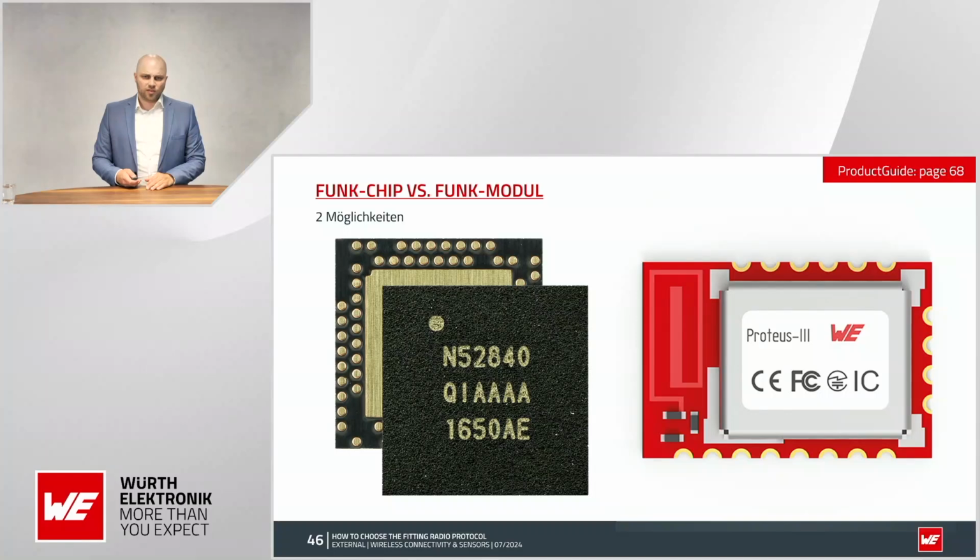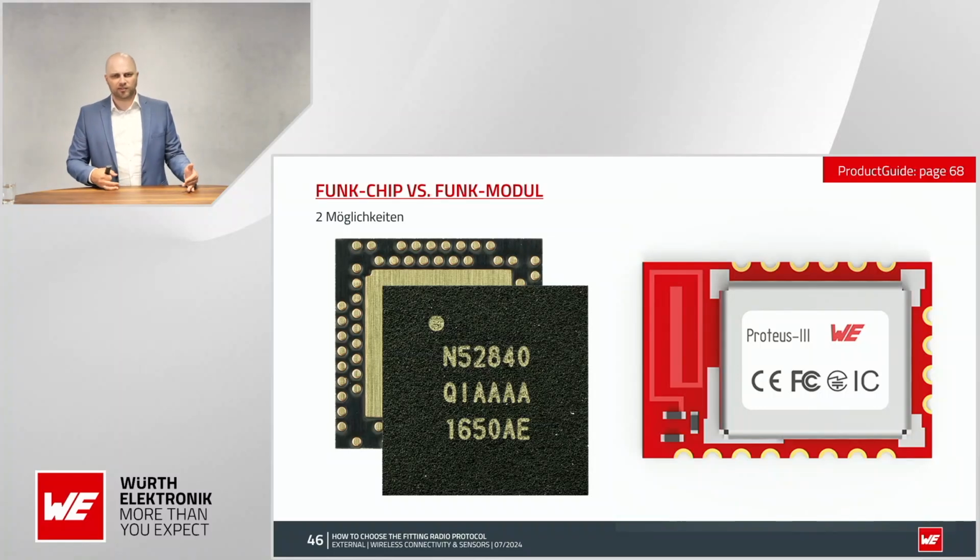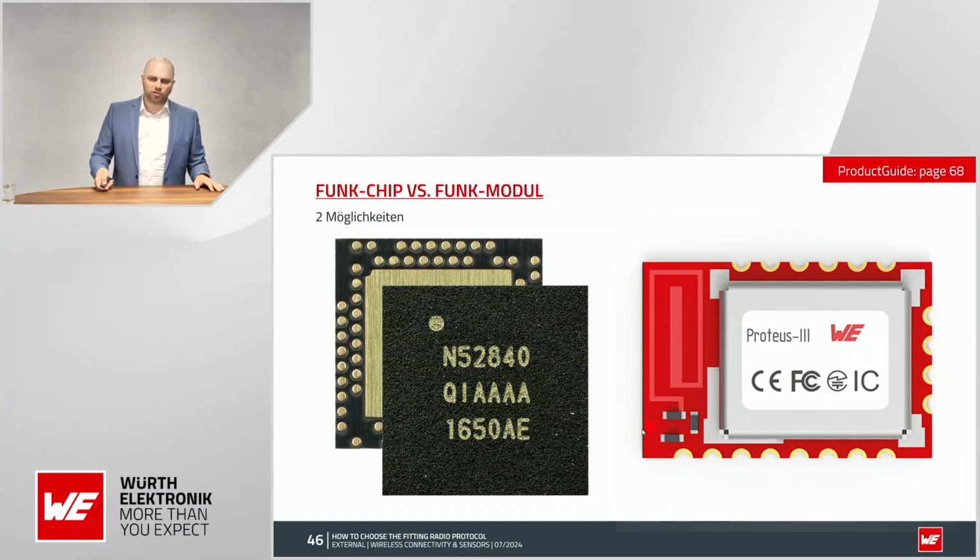On the other hand, with the radio module, you have a ready-to-use solution with an integrated antenna, for example, with the shielding, with peripherals on the module. But the disadvantage is you do not have the deep flexibility you have with the pure chipset. For example, not every pin is available on the module, so you have to work with what is available there.